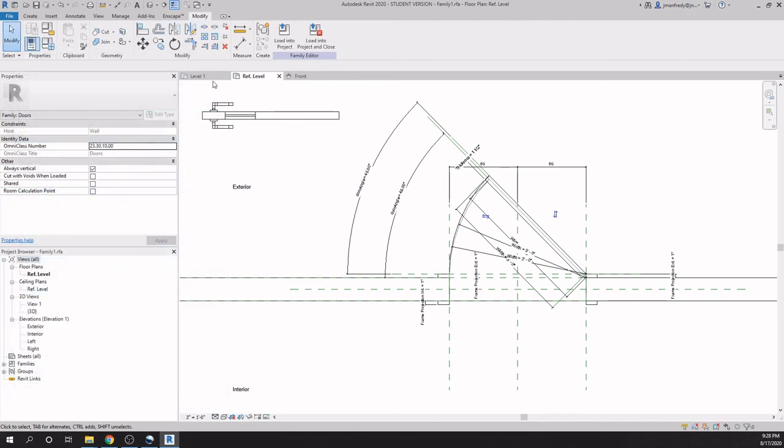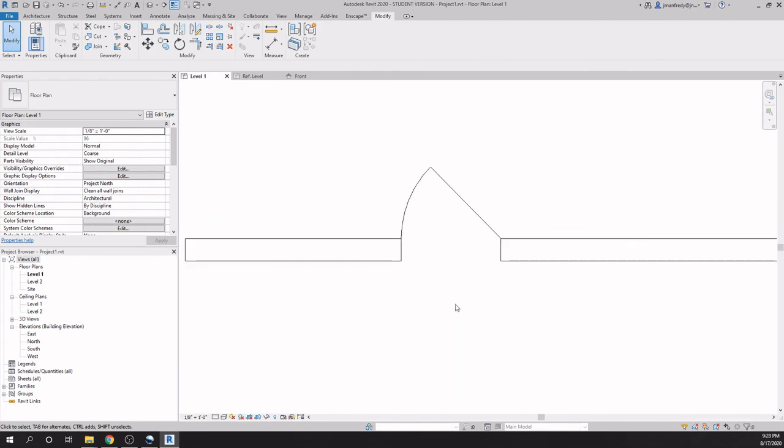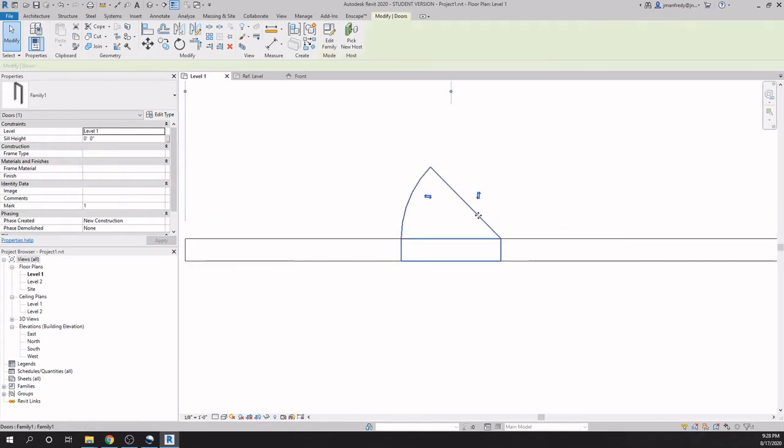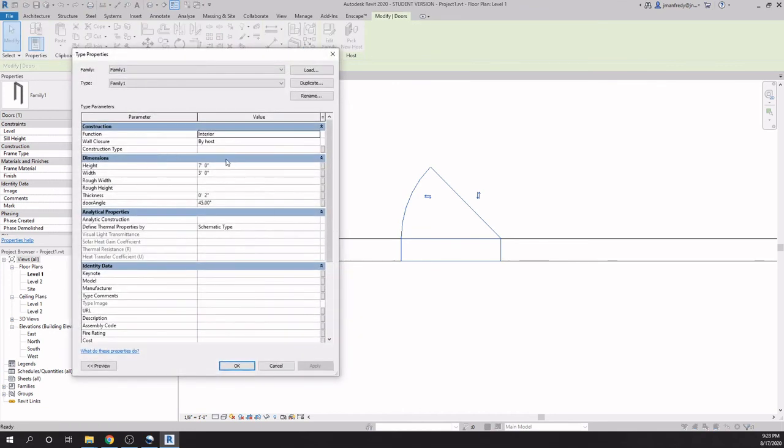Because, for example, if we go back to our project here, this is our sample project, if I click on this, I only have two areas to change this door. Either instance parameters here or edit type parameters here. And currently, there are no settings in this menu for the door's materials, door's glass material, the handle. They don't exist. They haven't been created.